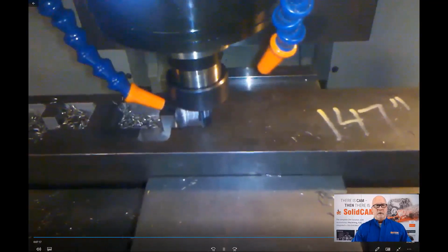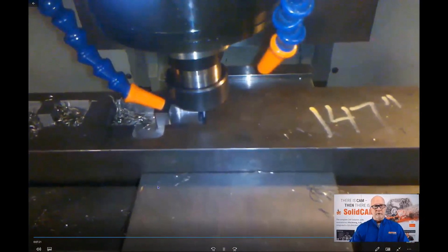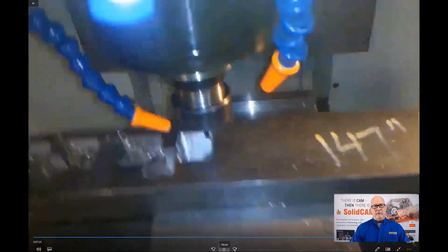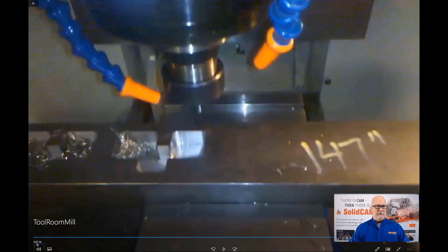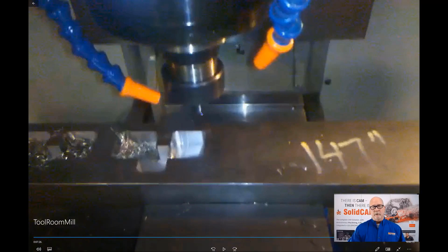All right. When we get down here to the end of the cut, notice the chip color is just absolutely beautiful. Okay. And as we pull off of this, we're looking at 7 minutes and 26 seconds cycle time instead of 2 hours and 26 minutes over here. The other thing that was really crazy about this, we pulled this tool out and looked at it under a scope, and you could not tell it was a used tool. I mean, it looked brand new. There wasn't even scuffing of the coating inside the chip ejection galley.